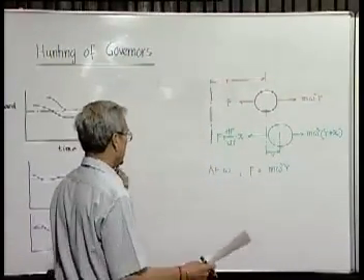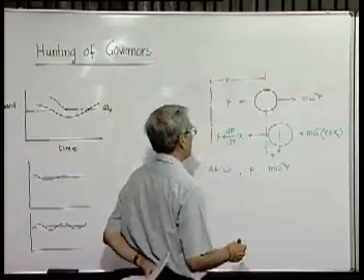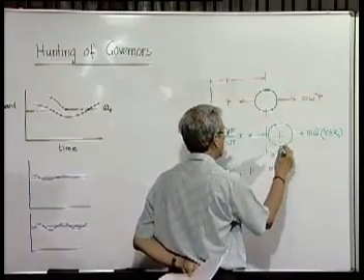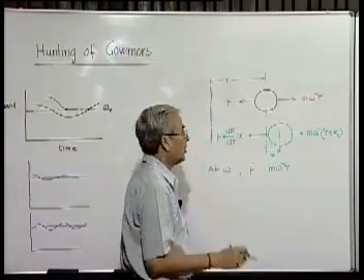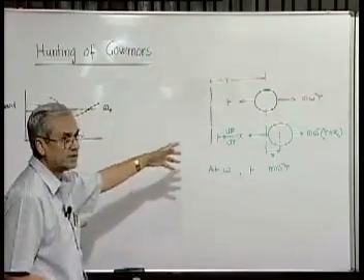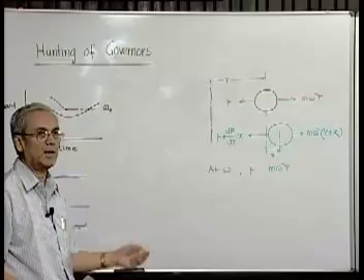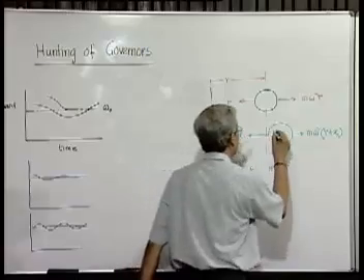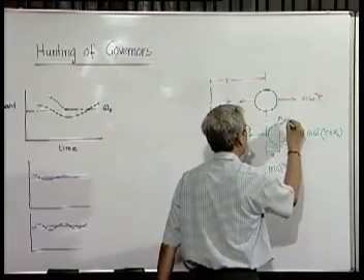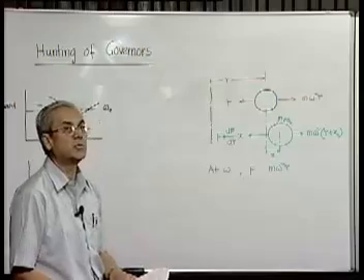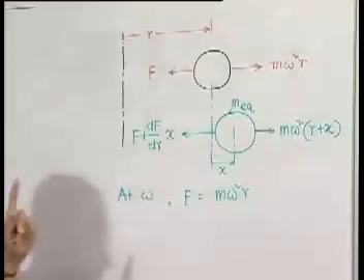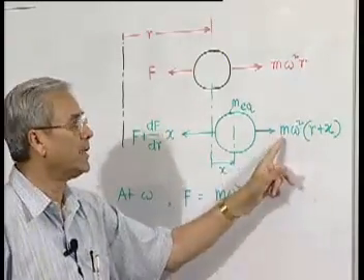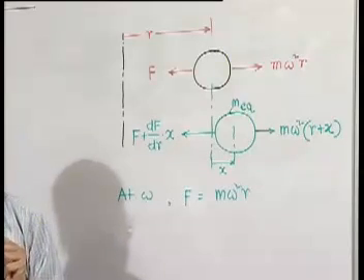that will give us the natural frequency. Now, one thing we have to keep in mind, the mass of the whole system represented by this is not the mass of the sphere, because there is a certain amount of matter present in the linkage, a certain amount of matter present in the sleeve, all those things. So all the equivalent inertia is accumulated on this body, and therefore we consider that its mass is equal to M equivalent. But the centrifugal force which is produced, which is trying to displace the whole thing, is actually from the mass of the spherical ball only, which we call m.